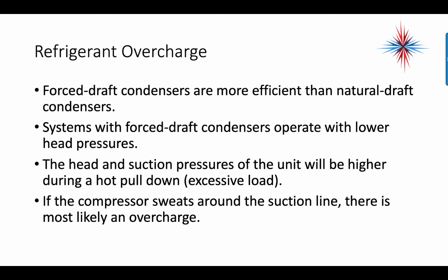Now, overcharges don't happen on their own. They're caused by technicians. So just be very careful. If you ever have a leak in a domestic refrigerator, the best thing to do is evacuate any remaining refrigerant, fix your leak, pressure test, do a soap bubble check to make sure you have no more additional leaks, and then once you have the system back in a vacuum, weigh in the proper charge according to the data plate. That is the only correct way to charge